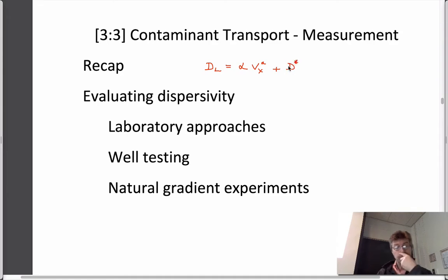So we've used that terminology throughout. And so this left-hand side is the mechanical effect by going in and out of the pores. The right-hand term is just Brownian motion, diffusion, by putting fluid in a beaker, which maybe happens to have sand in it, and so it can only diffuse in the tortuous flow path, although the fluid is stagnant within that.